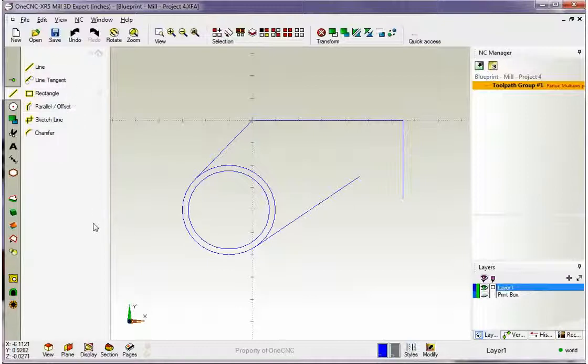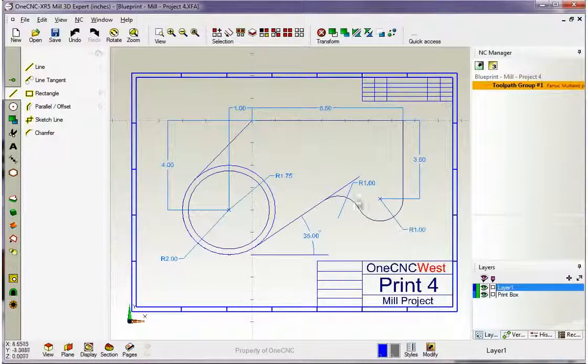It's very versatile. Alright, so let's take a look now at what we should continue on with. Let's turn our print layer box back on. Why don't we build this circle right here? This has a radius of 1 inch, and it looks like it's perfectly tangent here to this line, so we can use this radius value as an X value. So if we look at this value here of x 6.5, if we were to minus 1 inch, we would get x 5.5 for the x value.